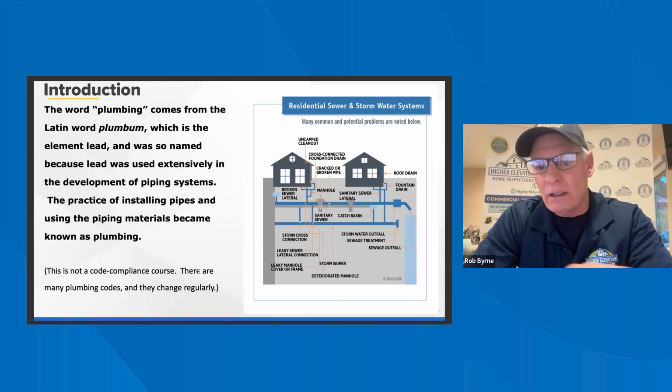Pipes used for water distribution are required to conform to NSF 61. Pipes used for distribution of hot water must be compatible with standing high temperatures. All hot water distribution pipes and tubing must have a minimum pressure rating of 100 PSI at 180 degrees. The maximum temperature of a hot water distribution system is 180.